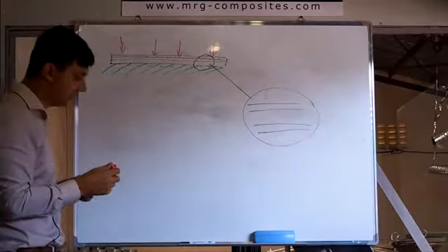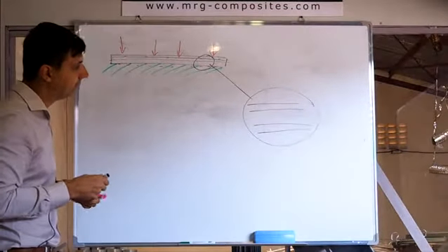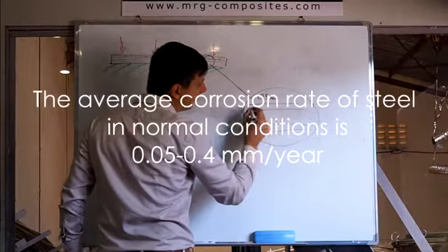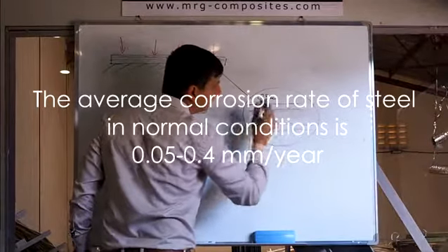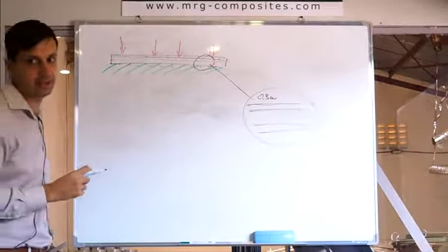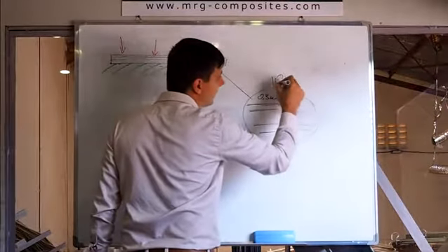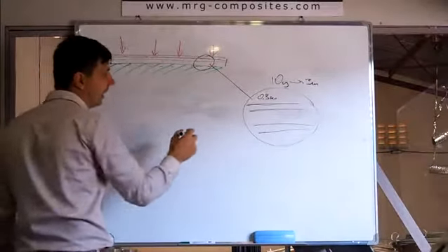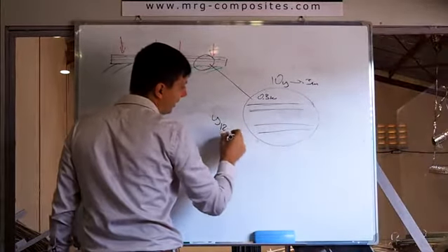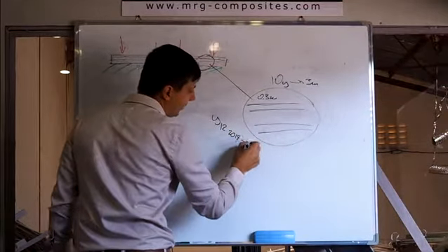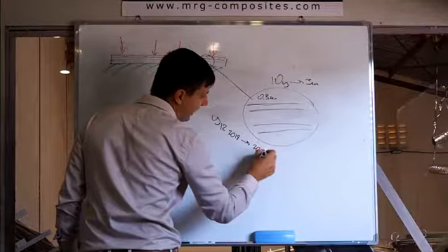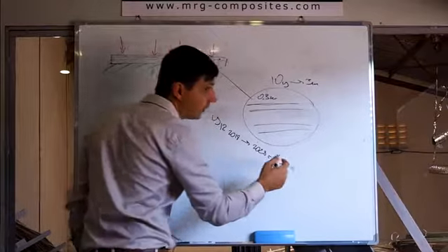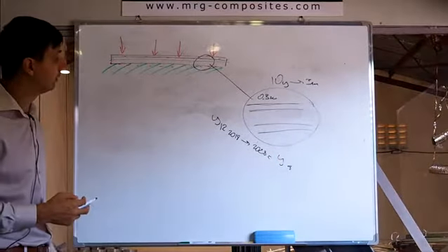So in this case, water will remove 0.3 millimeter of your bar every year. So after 10 years, you're going to lose 3 millimeters. Let's say if you have Y12 in 2018, in 2028 you're going to have Y9, yes, Y9. Whoa.